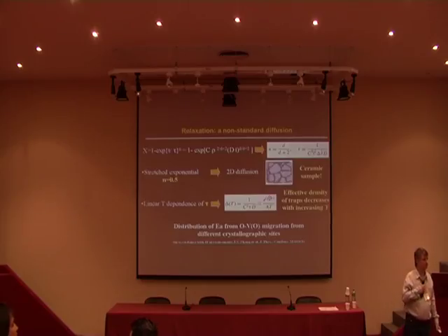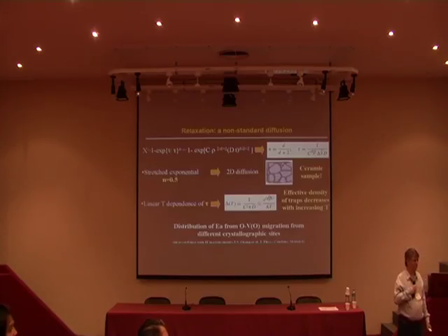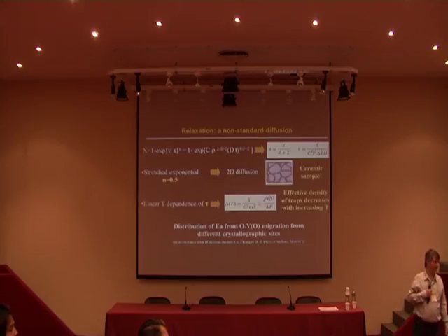It's actually more a comment on his question. In zinc oxide varistors, you are actually able to follow the conduction path after a threshold voltage. And you are able to see that normally they go through grain boundaries, but there's also some path in the bulk, even in bulk materials as well. And you can even follow that because there's light emission. We were doing some work like that. So in principle, it may be possible here as well.